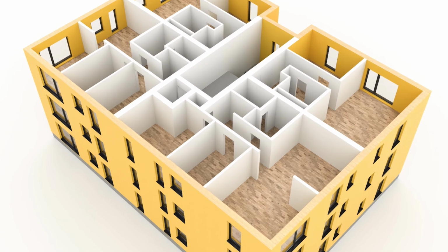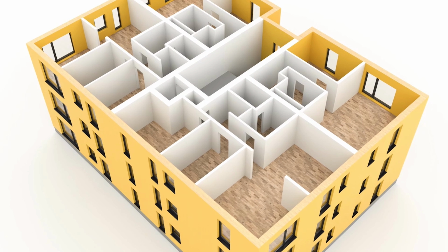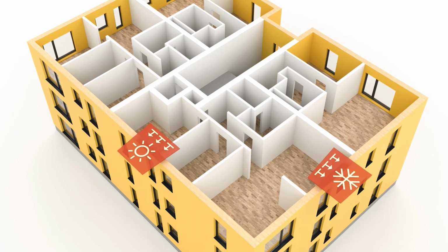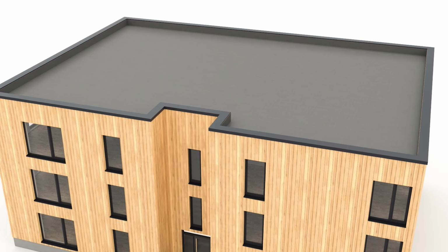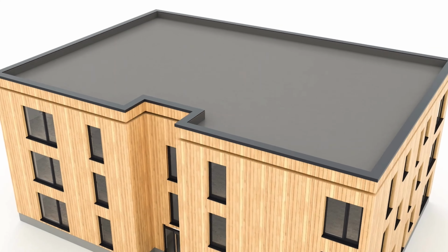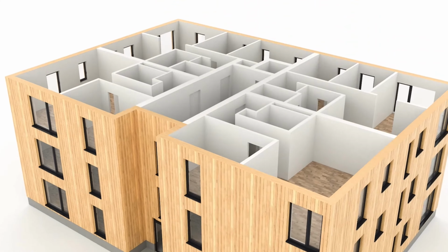Usually, exterior walls are designed also to provide thermal insulation, keeping indoor spaces warm in the winter and cool in the summer. Some internal walls provide sound insulation to minimize noise transmission between spaces. Some walls are constructed to resist the spread of fire, providing crucial time for evacuation and minimizing damage. The simplest wall type is a non-load-bearing internal wall, as that doesn't have to withstand a vertical load.